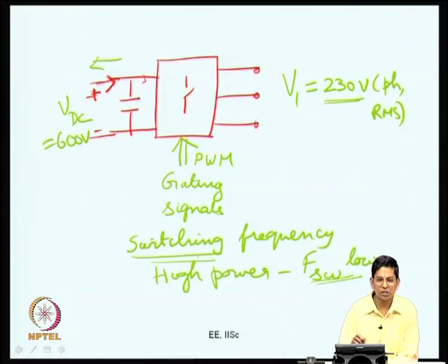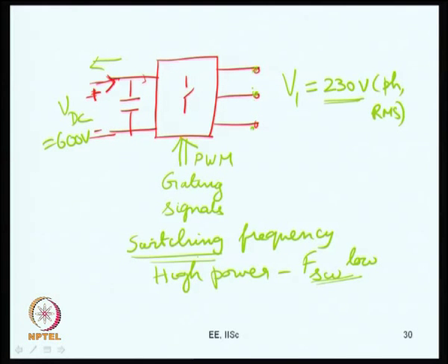And while coming to the PWM design, one thing that is of importance is also the application. As I mentioned a little earlier, if you are looking at a motor drive, the range of modulation matters. When you are close to the full speed of the motor, your modulation index is very high, you are producing a fundamental voltage close to the full voltage. If the motor drive is operating at a low speed, then the AC side voltage is very low. On the other hand, if you are talking of a line side converter, a grid connected converter, the modulation range is not very different. The frequency of modulation is always the line frequency, there is no variation, and the range of the fundamental voltage that you produce is within a finite range.